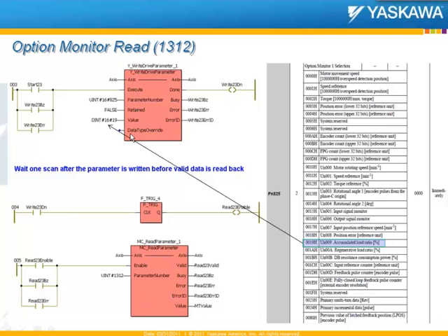What you see here, if this snippet is run in the program application, you would read the RMS torque here. Of equal importance, another important term that can be read back from the servopack is the regenerative load ratio, if regenerative resistor packs are used in the application.